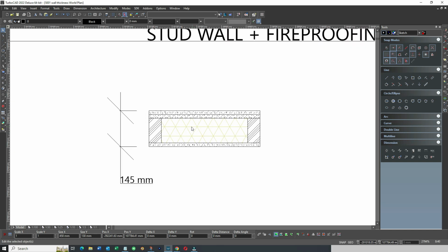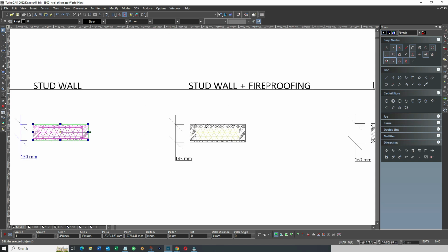And by the way, this comes up a lot for us when we're doing conversions, because part of the fireproofing means you have to build up the 30-minute fire protection on walls surrounding stairs, landings, anywhere where lots of people are moving around. So you've basically got to beef up the board, two layers of the pink. So you end up with 145. So we tend to allow 150 for these particular walls in the hallway.